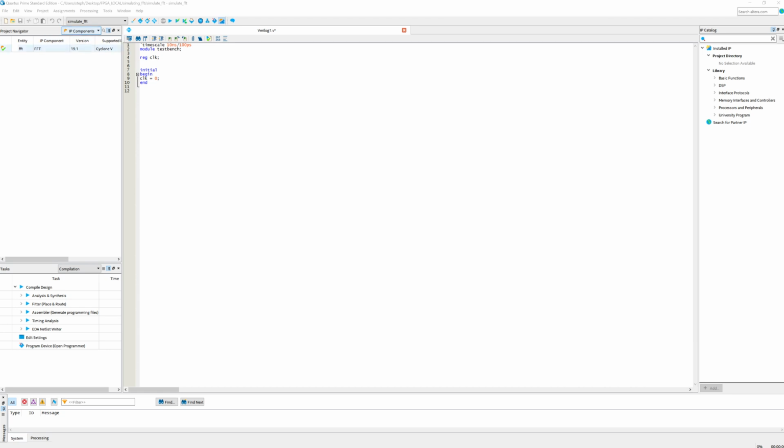And that's quite convenient, because if you want to change this megafunction later on, all you need to do is go into IP components, double click this, and the IP parameter editor will open up again, and you can regenerate as necessary. So that's a good thing to remember.